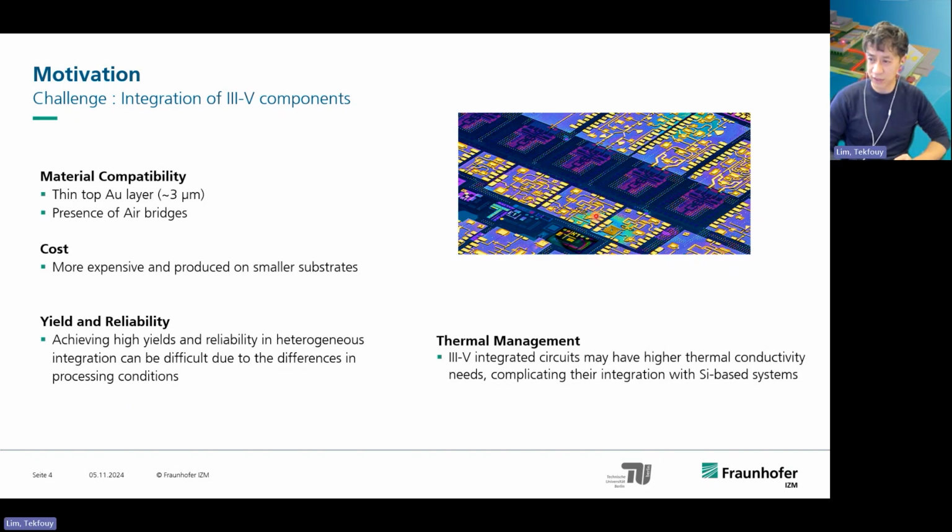Since the back-end of line doesn't have a lot of metallization layers, these circuits usually have a lot of air bridges. And the problem is that if we really want to use it in integration, and there's a little bit of pressure on it, the air bridges can be damaged, and then the whole circuit will not be functional anymore.